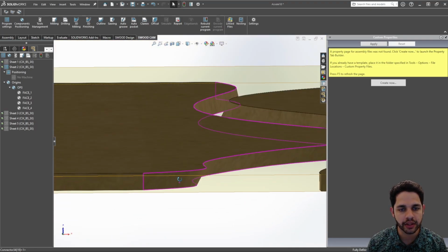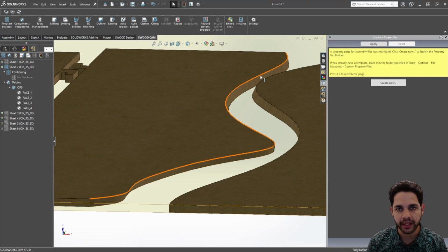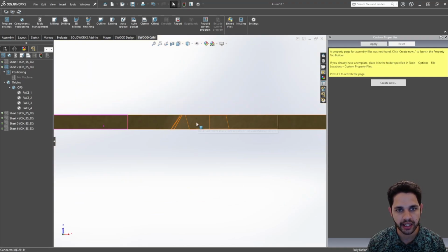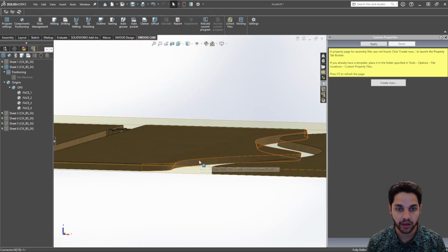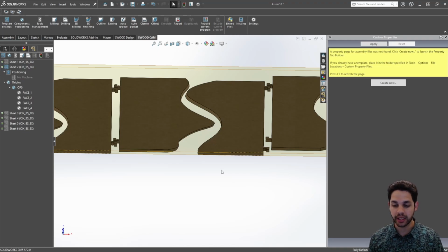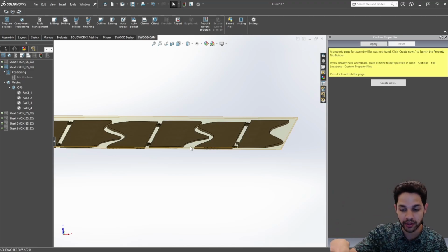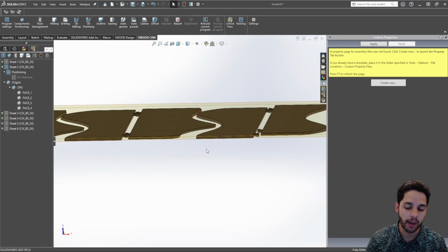One thing to notice, like when I did that split using that plane, if I look at the panels, you can see that they're kind of cut on an angle. There's a couple different options. If you wanted to keep this angled cut, you probably need some form of a pod and rail machine, so that way you can have some five axis functionality to come through and actually cut these on an angle.